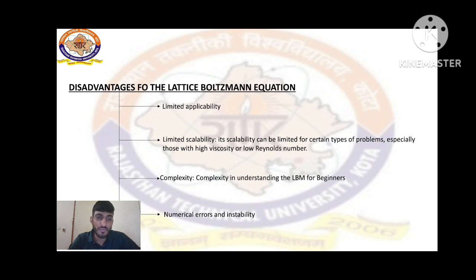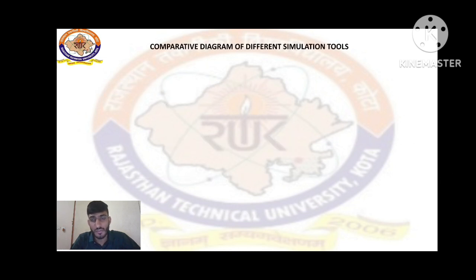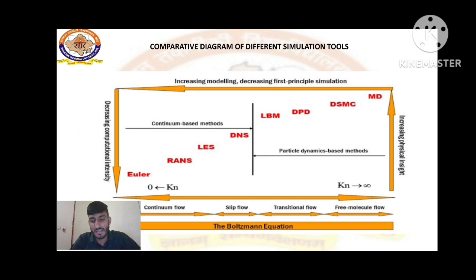Now we go through heat transfer, reaction, diffusion, and phase transition phenomena. There were two mostly used methods. One was the multi-speed Lattice-Boltzmann thermal model, and the other one was the enthalpy-based Lattice-Boltzmann method. These two methods were the most discussed to simulate heat transfer, reaction, diffusion, or phase transition phenomena over here. And now we discuss a different kind of approach, which was the finite difference lattice Boltzmann method, which was used to simulate flow using an unstructured grid. This was one method that can also be used to simulate compressible and shockwave flows, but further study is needed for this.